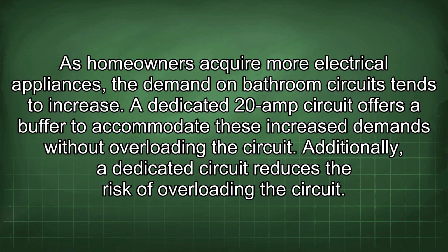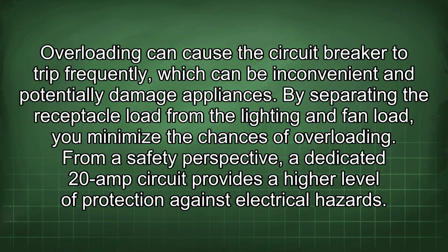Additionally, a dedicated circuit reduces the risk of overloading the circuit. Overloading can cause the circuit breaker to trip frequently, which can be inconvenient and potentially damage appliances. By separating the receptacle load from the lighting and fan load, you minimize the chances of overloading.